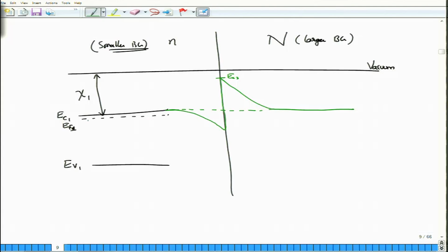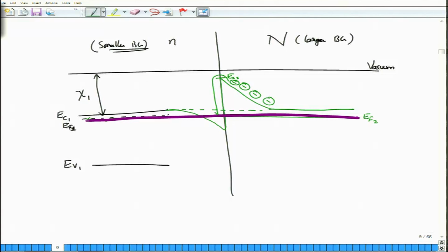What about the Fermi level? Well, we draw the Fermi level here. So, this is my Fermi level overall. As you can clearly see, EF1 and EF2 are the same and they are constant. Now, look at this very interesting thing. The Fermi level is lying above this well. What does it mean? The Fermi level tells you that this is the region where 50% of the probability happens, but because there is a well here, what has really happened is that the electrons which are having a smaller affinity have actually moved and then fallen into this accumulation region.